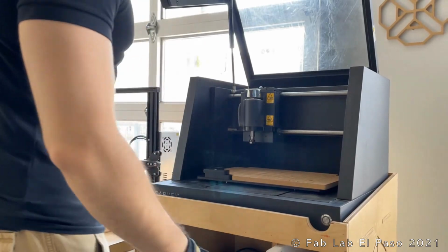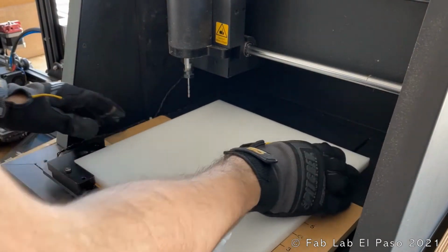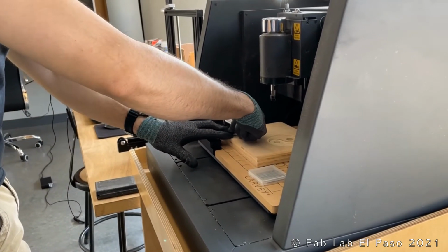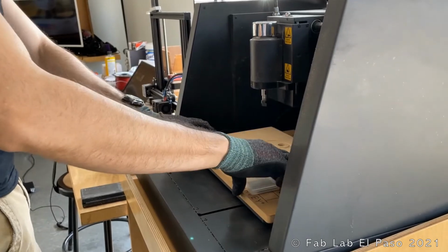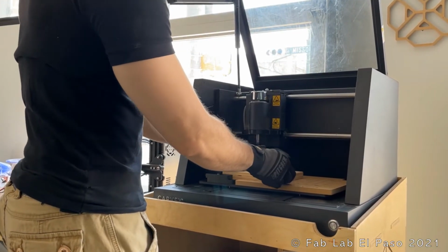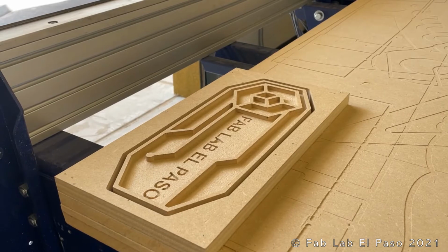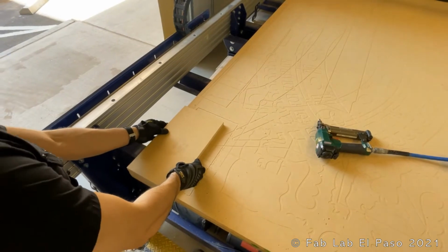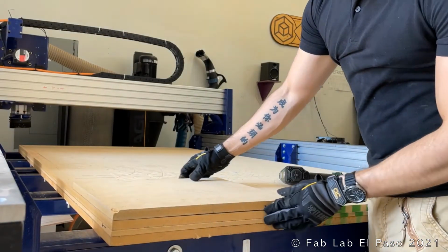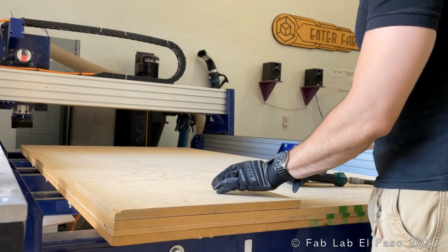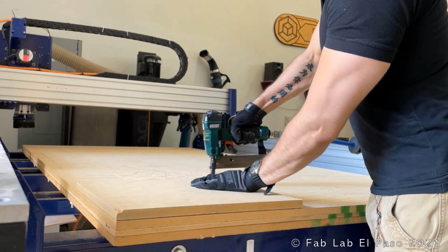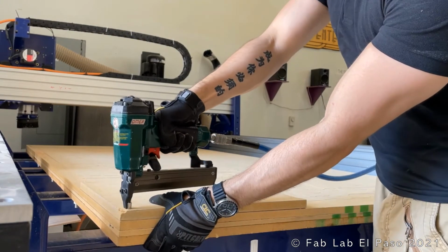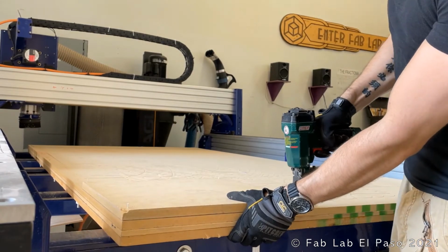It is convenient for small parts, but what I want to do, I cannot do in here because it doesn't fit. If you only have access to a machine like this, then maybe you split your file in half and then glue it at the end or use screws. But anyway, we know that our equipment is capable of creating this part, and I know that my file is about 13 by 6 inches and the material that I have is 15 by 8 inches, a little bigger than the part that we're creating, but that's what we need because we want some extra space for adding the nails around and tabs, and just so you have a little bit more room for errors of positioning.